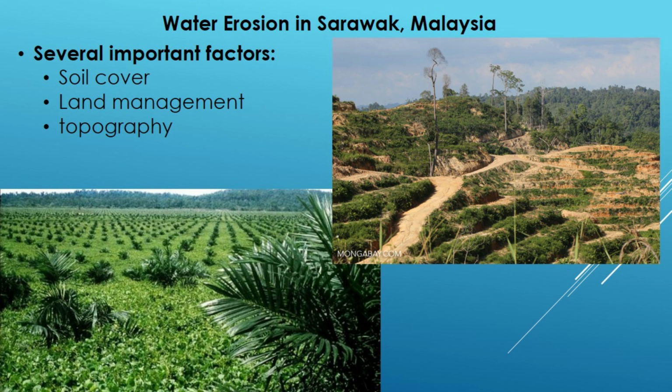When the slope is longer, the surface area for water collection also increases, and therefore the runoff volume increases. Further, land management refers to things such as massive land clearing done by large construction equipment, which pulverizes the soil and clears all the vegetation. This mechanical disturbance exposes the soil directly to the impact of rainfall energy.